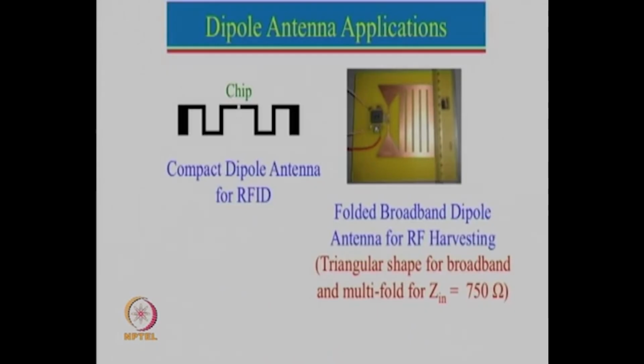Dipole antennas have been used in Yagi-Uda antenna to design a directional high gain antenna. Dipole antennas are also used in log periodic antenna to obtain an ultra broadband antenna. Modification of dipole, for example a conical dipole, can be used for broadband application. But now some other applications of dipole antenna are also emerging.